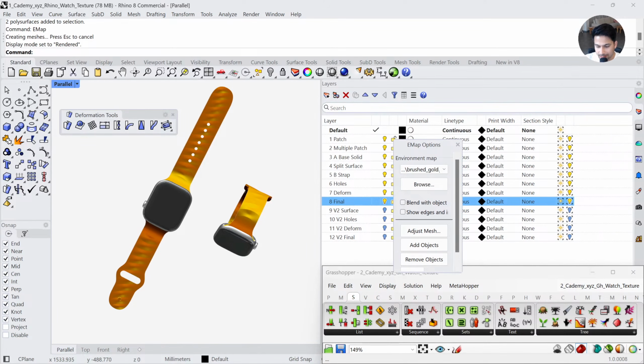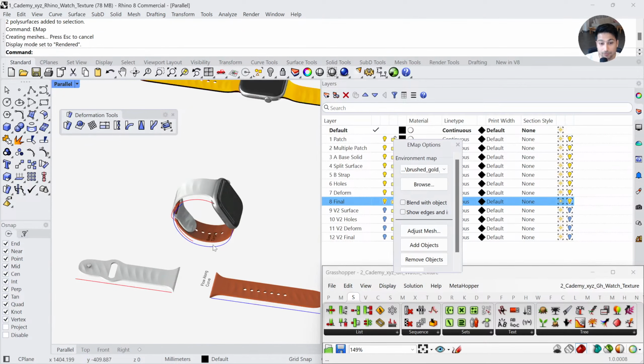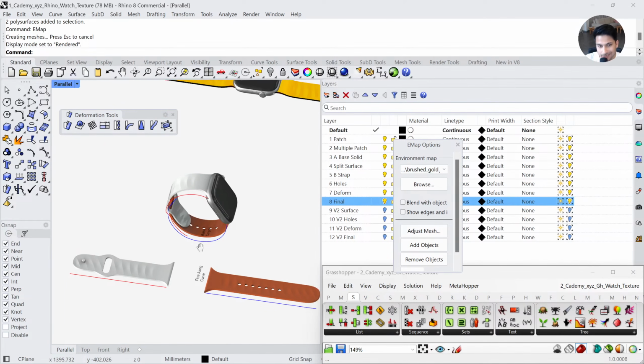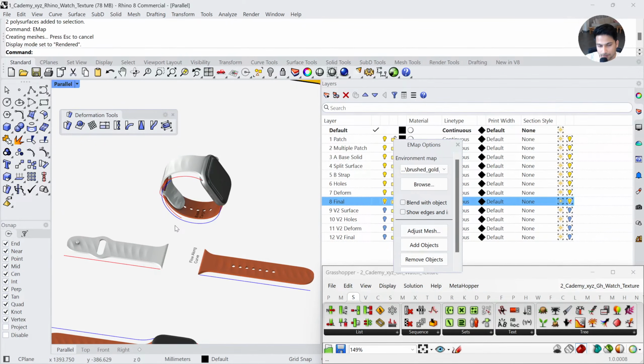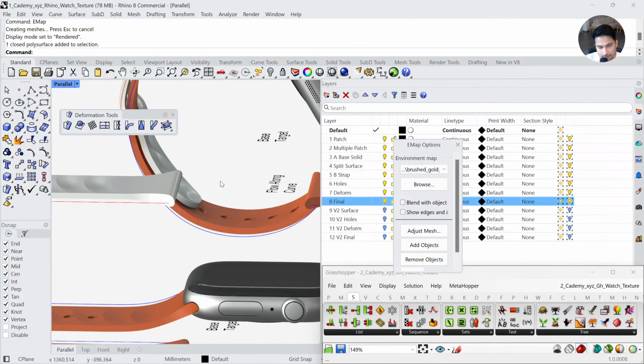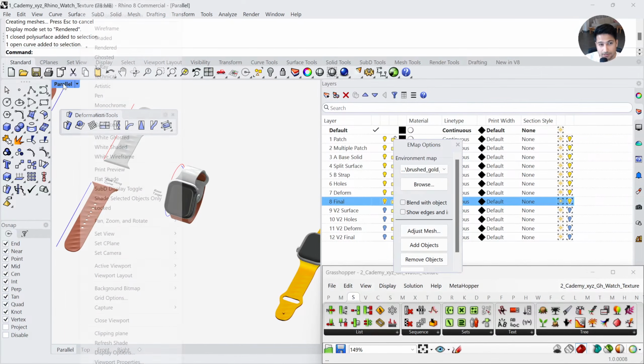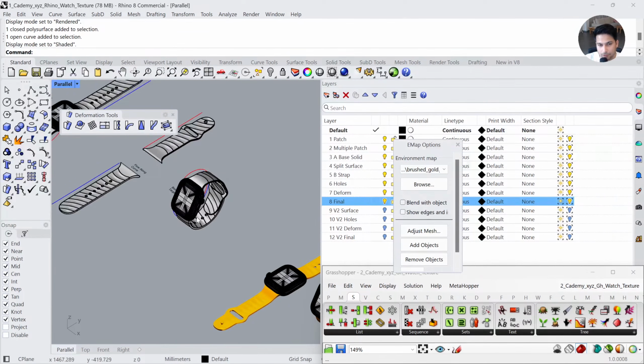How to bend the exact length for the wrist? I mean, what you can do is if you turn off the stretch option, it will automatically stop until it reaches the length. Okay, so here you can even see that it's probably a bit longer than the base curve. So yeah, the flow along curve command will automatically stop if the stretch is turned off.